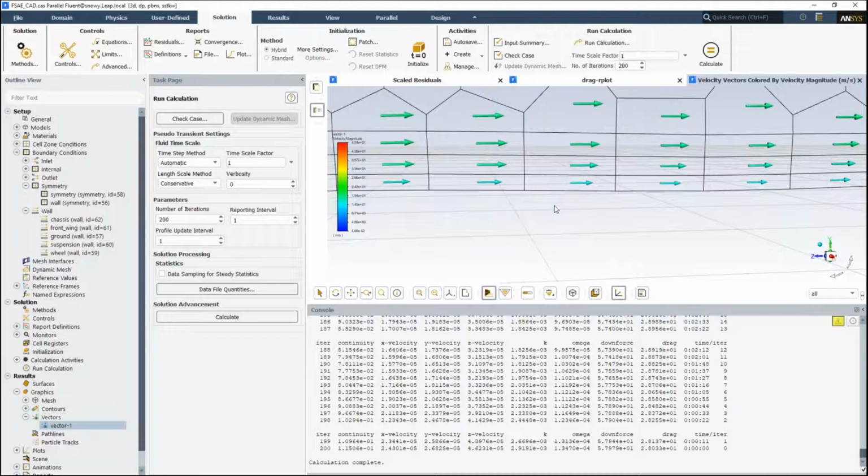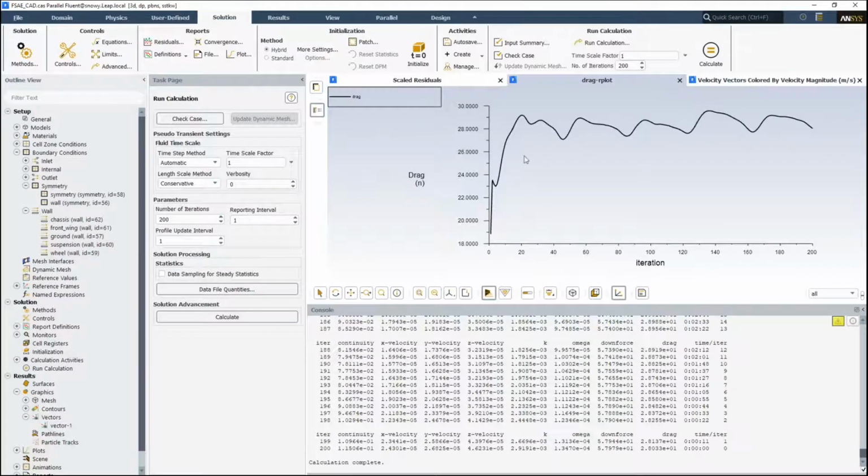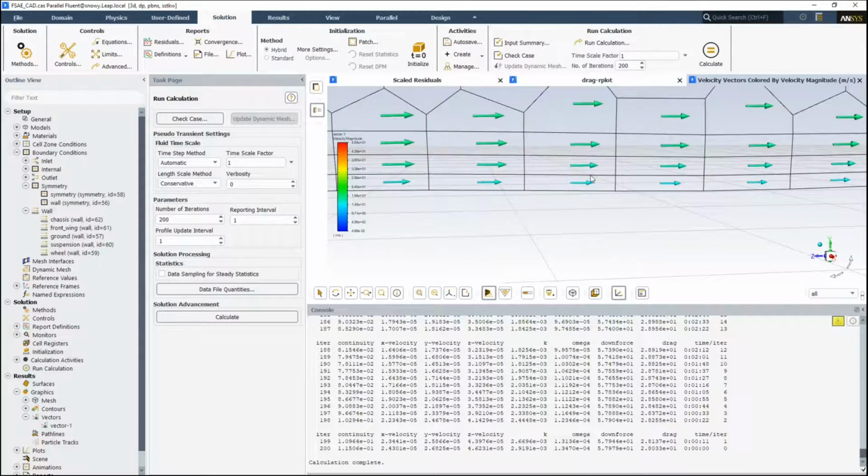It's hard to make general comments about it, but there's things to understand, like a turbulent boundary layer will stay attached for longer but will create extra drag. And all of that happening in the boundary layer can have huge implications for what these results are. So if we're not picking up the boundary layer accurately, we're changing where the flow is separating, how much friction drag there is from the airflow on that surface, and we're changing our result. So there's a lot happening in the boundary layer, and picking it up accurately is very important, especially for things like external aerodynamics. Cool.